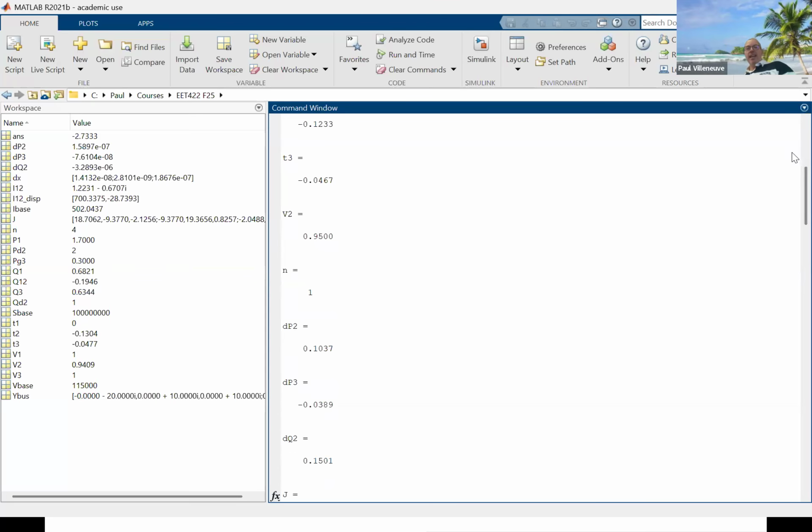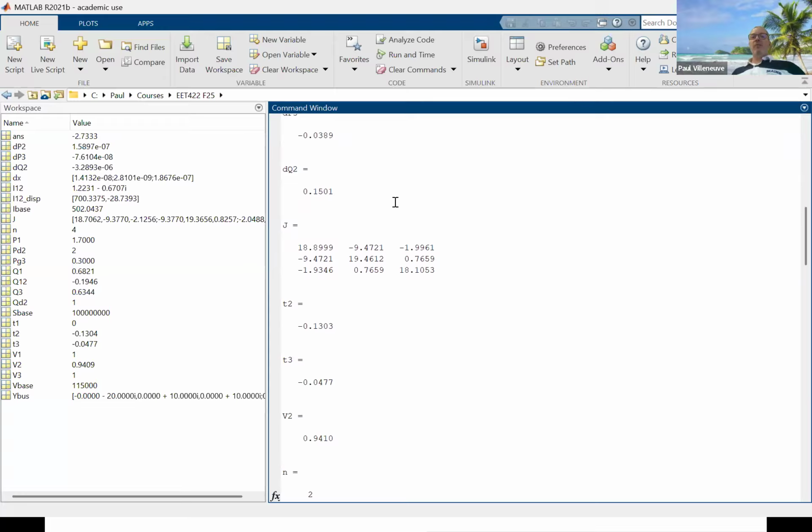That's okay. Now my power balance was at 2, 1, and 0.3. Now I'm a lot closer just after one iteration, but not close enough. And you can still see, remember we had 20, 10, 10, 20, and 20. So the Jacobian was updated, but it isn't a huge change from your original Y-bus values, right? So that kind of lends credence to maybe I could just use my 20 and 10 values and see how close I can get to be accurate. Let's keep track of that on the way through.